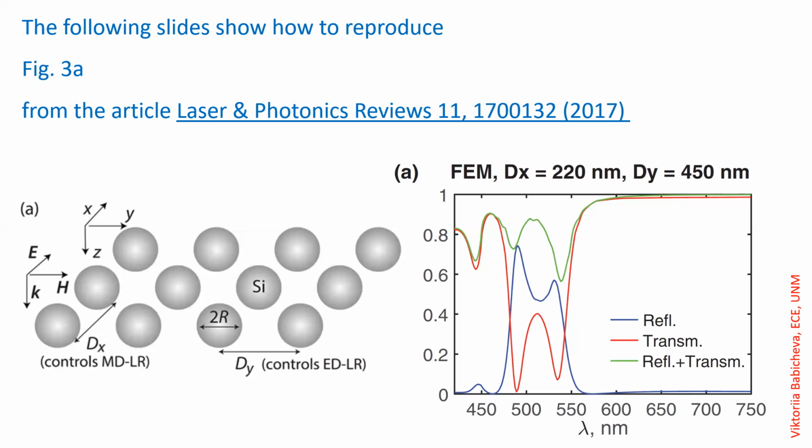To perform simulation of the periodic array, we place only one antenna in the domain and impose periodic boundary conditions. In the simulation domain, we set up physical objects, which is an antenna in our case. Next, we add a substrate and superstrate for correct spacing between the object and the domain boundaries, as well as the convenience of meshing.